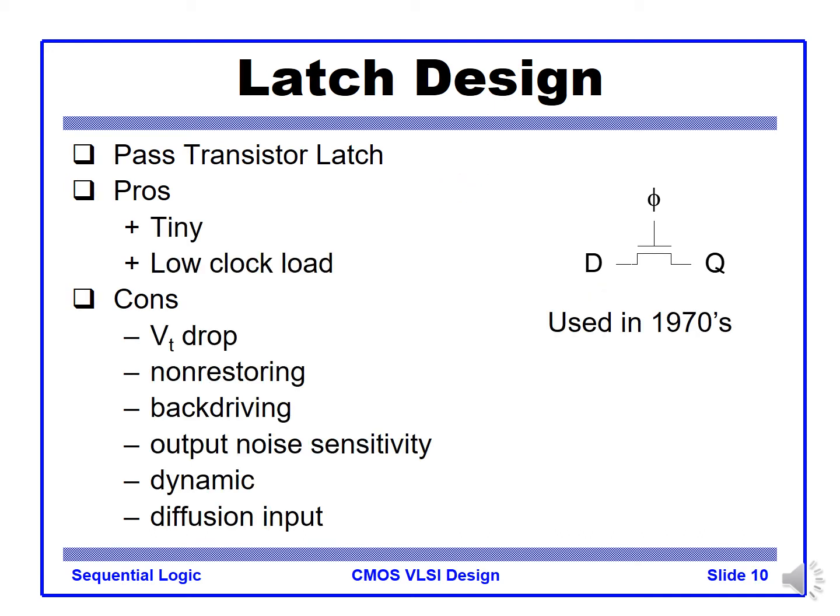The advantage is it's very tiny with low clock load, because the clock signal only goes to a single MOS device, so it has a very low clock load. Actually, this kind of thing was used in the 70s, but the problem is it has a VT drop for passing VDD, right?